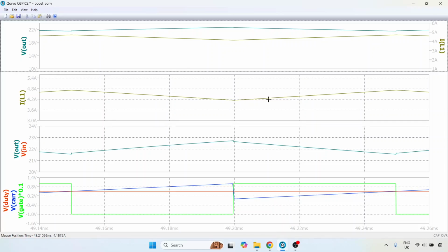There are certain issues, like for example, where are we losing 1 volt? That is of course an issue, and you should investigate it. You can always decrease the resistance of the inductor, or the series resistance with the inductor, in order to see if that decreases this particular drop. I will leave this to you as an exercise. I will stop this lecture now, and in the next lecture I'm going to talk about one other issue,